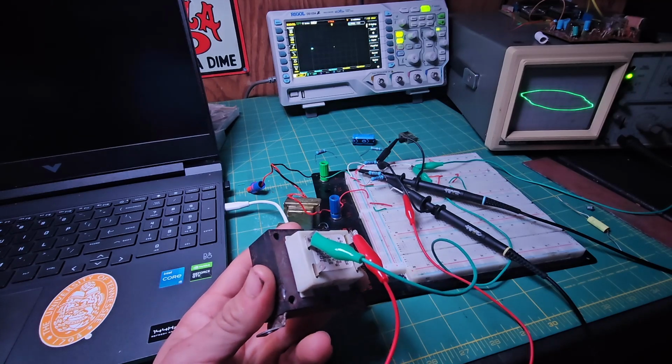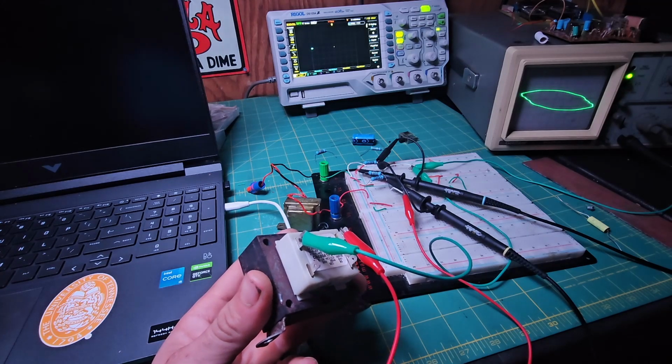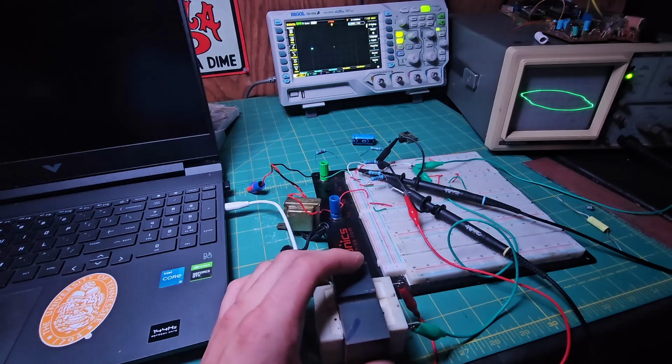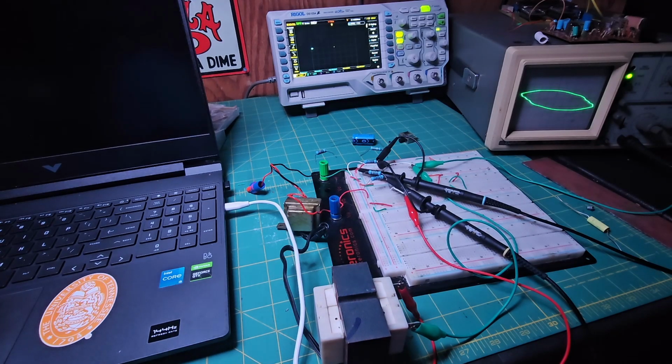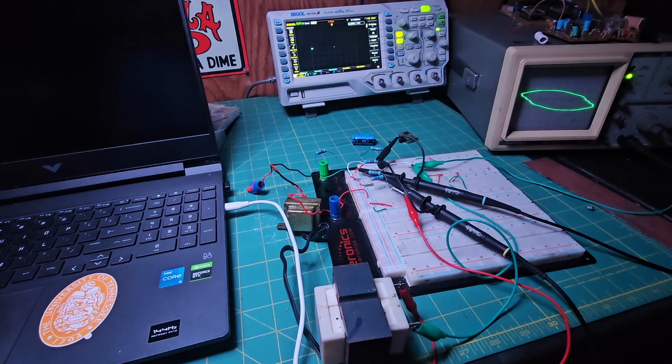The only difference is the current and voltage is flip-flopped. So that equation that I told you, IC equals C times dV over dt, the same equation applies to inductors, but the terms are swapped around. So with an inductor, it is VL, so the voltage across the inductor is equal to its inductance times di over dt. So they're very, very similar. In a lot of ways, capacitors and coils are mathematical mirror images of one another, if you will. But yeah, hopefully that clarified what I was talking about.